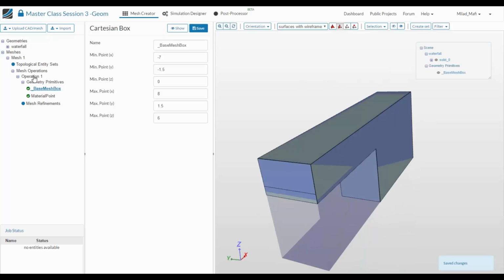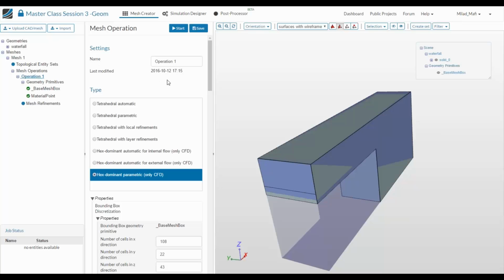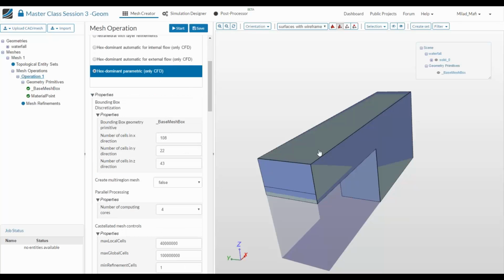And the next thing is, if you remember how snappyHexMesh works, we have to define, first of all, a base mesh size by giving the number of elements we want to divide this base mesh box into in x, y, and z direction. So for x direction, we can also keep it like it is. You can calculate the actual mesh size very easily for level 1. For example, we have a total length of 50 meters in x direction, and if we just calculate it, our initial length in x direction is 0.13 meters.